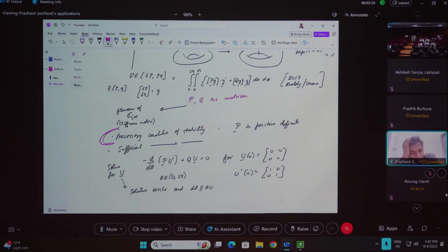So, eigenvalues of the stiffness matrix being positive, or C_ij, or P being positive definite. This kind of thing is seen pretty much everywhere. So the necessary condition is very, very well known and people have been using it forever. But the sufficient condition is not very well known, for this very reason that it's so super hard to work with. But if you work with it, then you can actually get a really correct answer to the problem that you have.